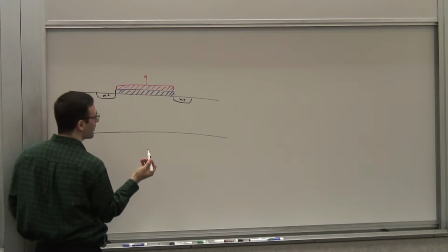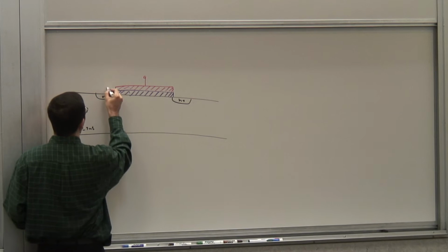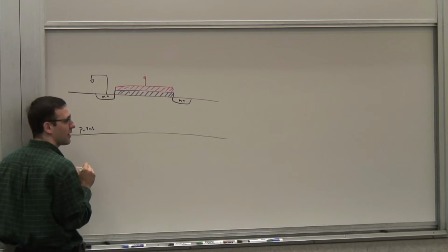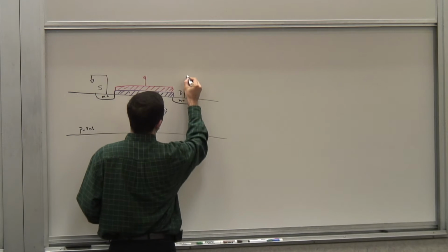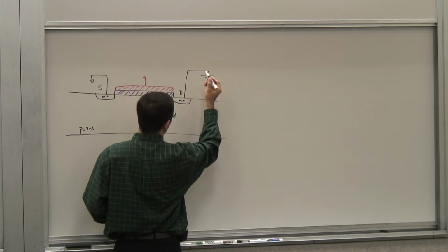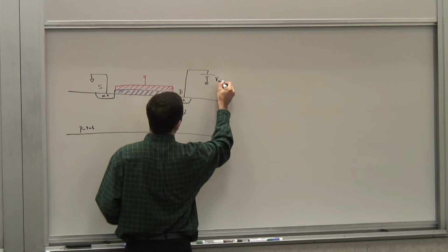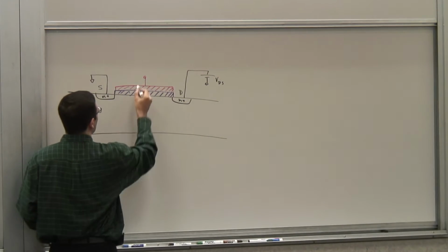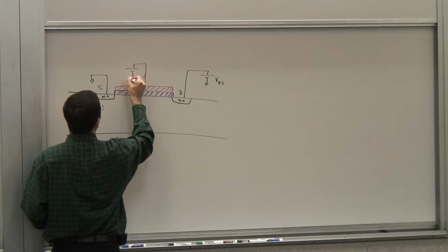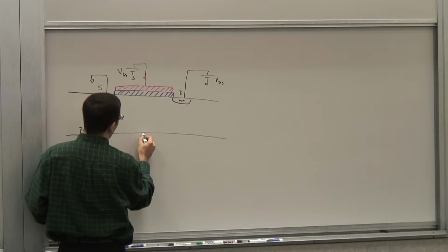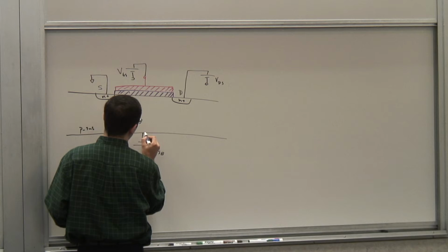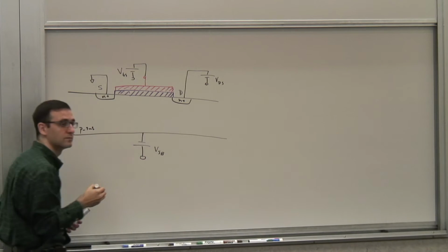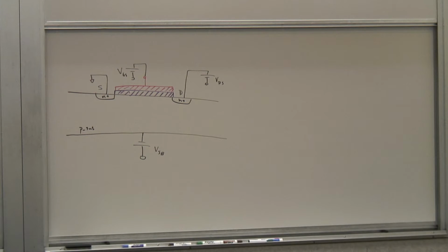And therefore, there are 4 terminals involved here, right? You got the source, which we decided was a reference potential. So this is the source. The drain, which we said in general could be connected to a potential VDS, reference to the source. The gate voltage, which was VGS, again reference to the source. And VSB, between the source and the substrate. Right? So you can see it's a 4-terminal device.